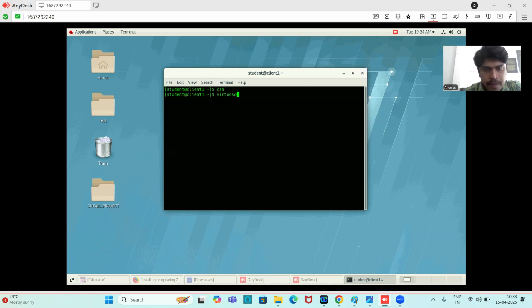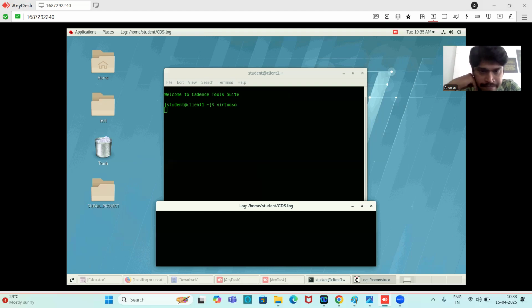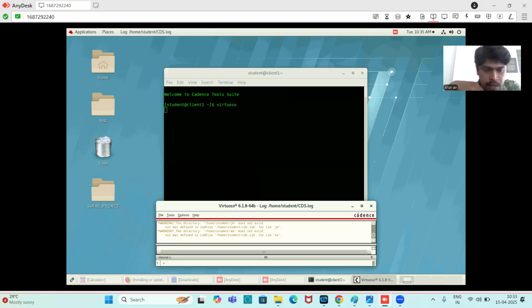Then source /home/install/cshrc. Then invoke the Virtuoso. So this may take some time. Okay, so the Virtuoso portal is opened.